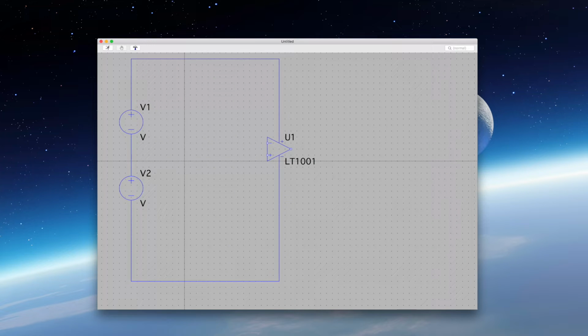Okay, for this to work, we're going to need a ground. So let me just put an extra wire here. Just go from here to here. And I'm just going to go this way. Just hit escape. And I'm going to put a ground in the middle, which is really a reference. So I am going to go to net name, pick a ground right here, and stick it at the end of this wire. So this will be our reference here. If you measure here, you will get whatever this voltage is as a negative value, and this one, whatever this voltage is, as a positive value.